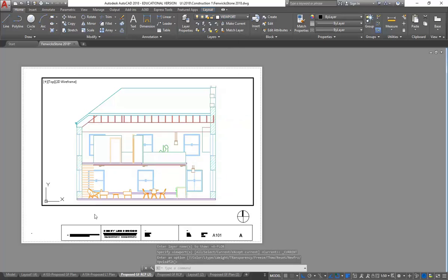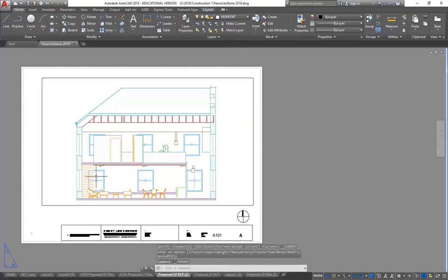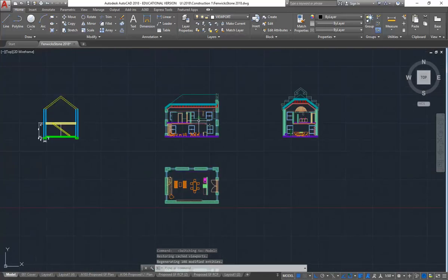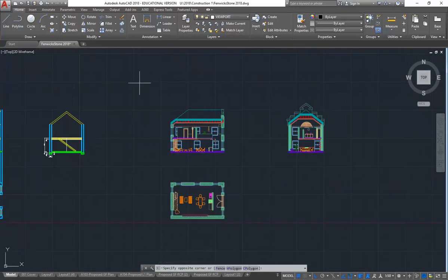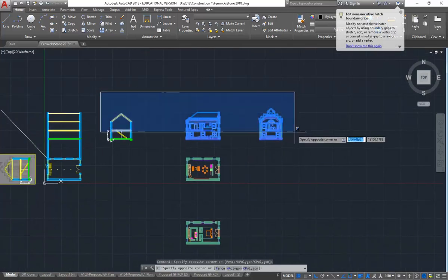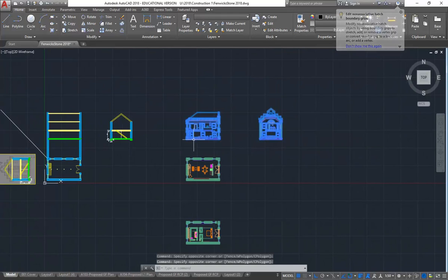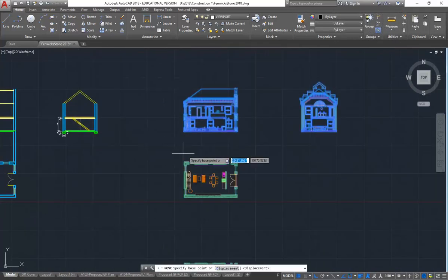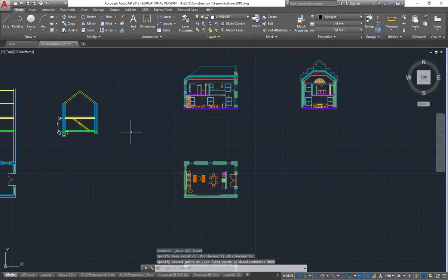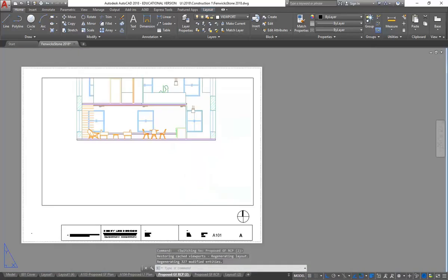Yeah. So, okay, so again here we've got the section showing up just fine on this sheet, but now if I go back and move that section, so let's say I need to move it, move the whole thing up to allow more room for us to do some more drawings. So I'll move, in fact, I'll just move those two, so just with the Move tool. And so again, I'll just type in a round number, 5,000 this time. So I've got some more room now, but of course when I go back and look at this on the new page I've made, the section's moved.